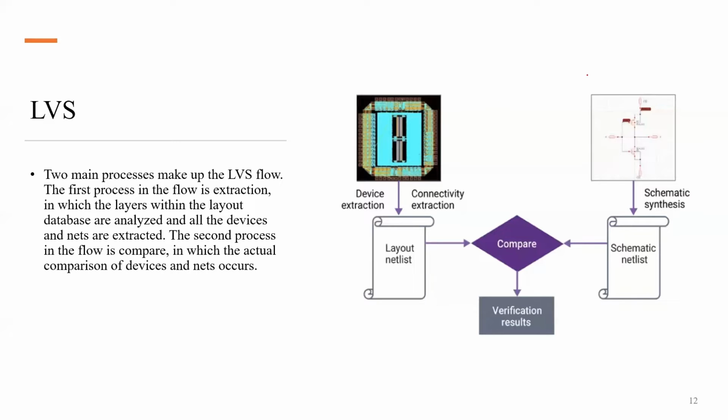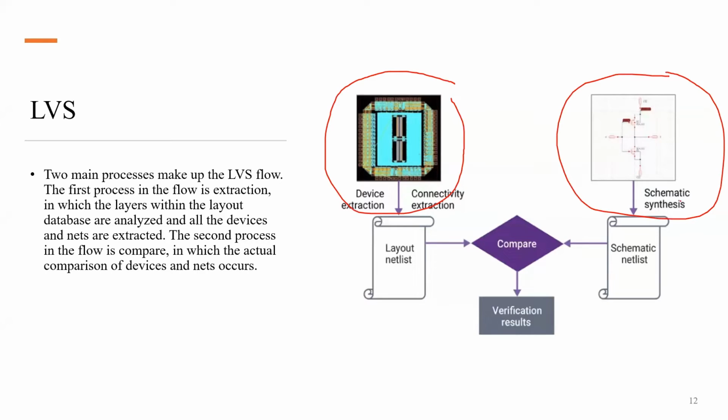In this one, we take the netlist of the schematic. Suppose this is a netlist with node points defined in SPICE format. We get the netlist of the schematic, generated from the tool. Then we take the layout extraction file and put it in the comparison tool. It will compare the connections of the layout with the schematic, and it will give the result of the LVS.